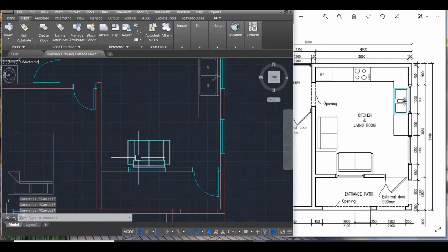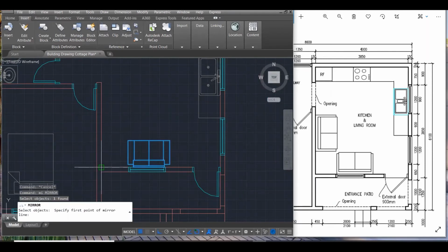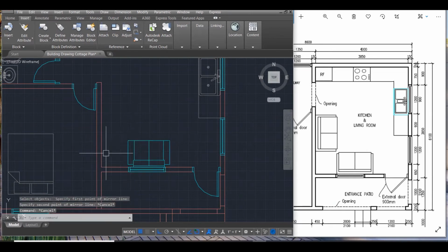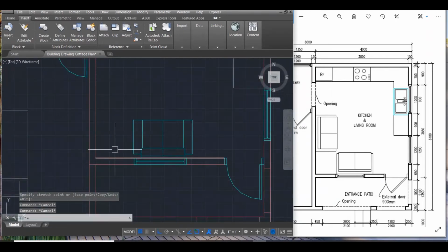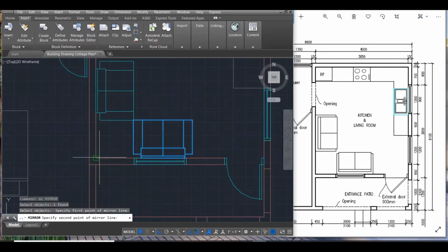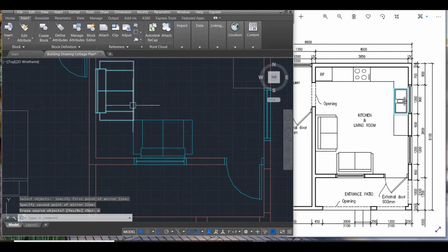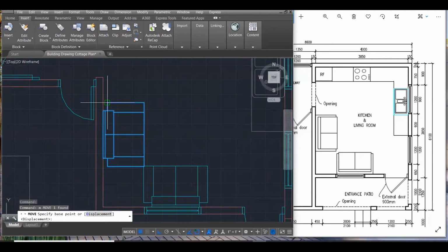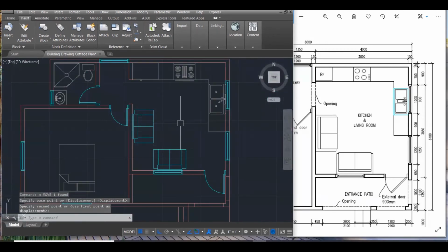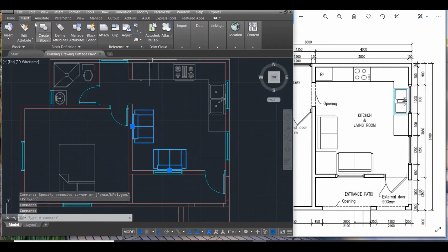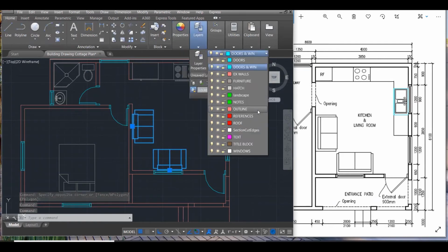And then I'm going to mirror this now. Like that. I know how to mirror this. I'll drag this to there temporary. Then I'll mirror this. Mirror. Blam. No. Then I adjust this by pulling this up, moving this up. And that would be the living room complete. So grab these and put these into our furniture layer.